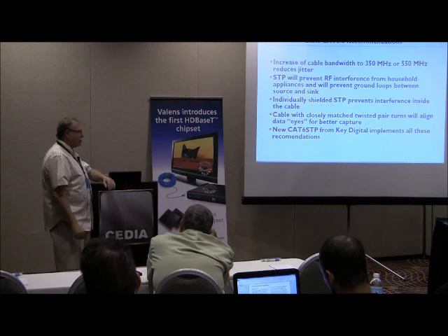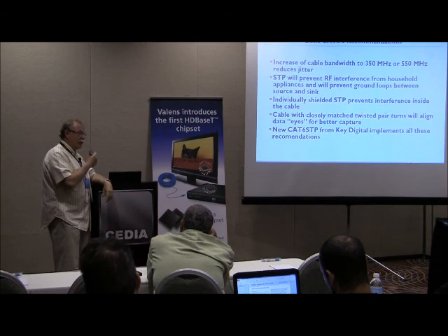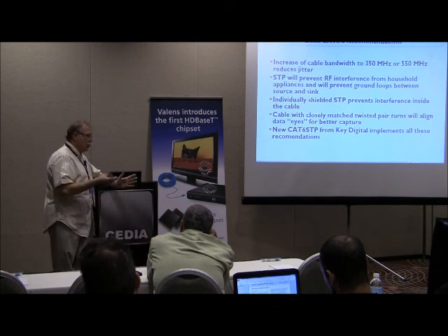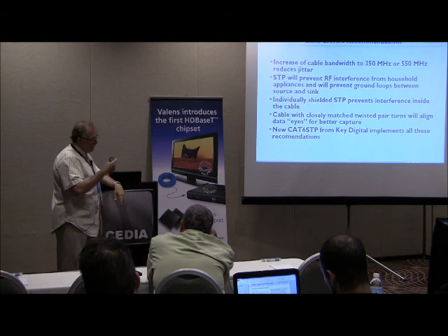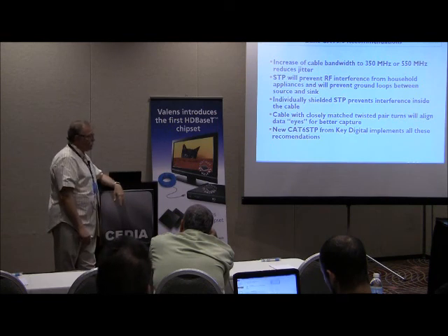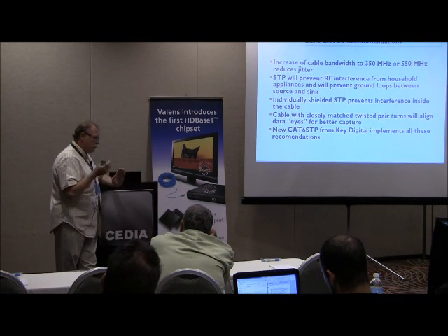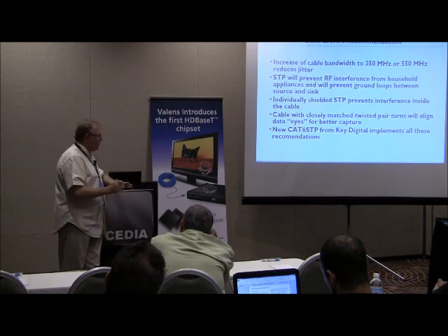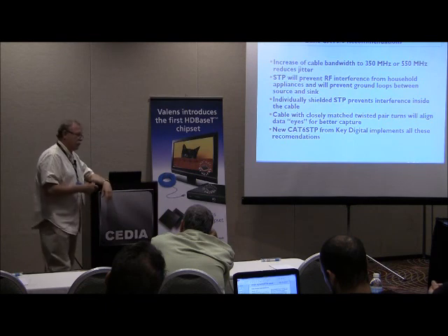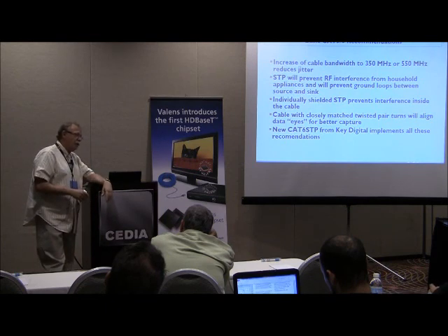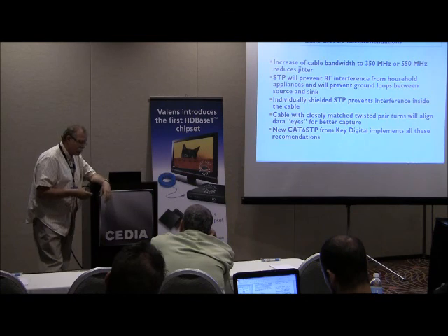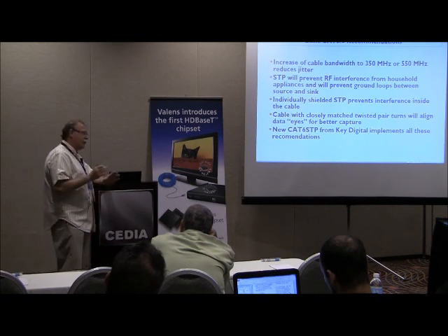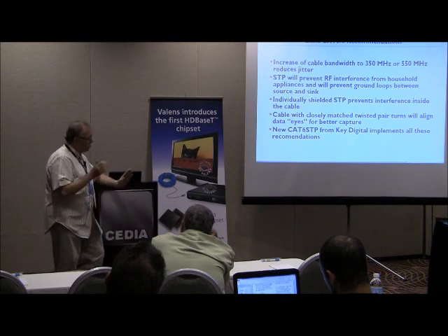So at some point we started to recommend shielded STP, which is a good way of preventing some mistakes. And finally, we decided that to guarantee the absolute top performance, we're going to make cables that we make ourselves. We know how to make them, how they work. We tested with all our products. And that way, we feel most comfortable. When we do big jobs and people buy a large matrix switcher from us, we're just telling them, look, we're not going to sell you a matrix switcher if you don't use this cable.